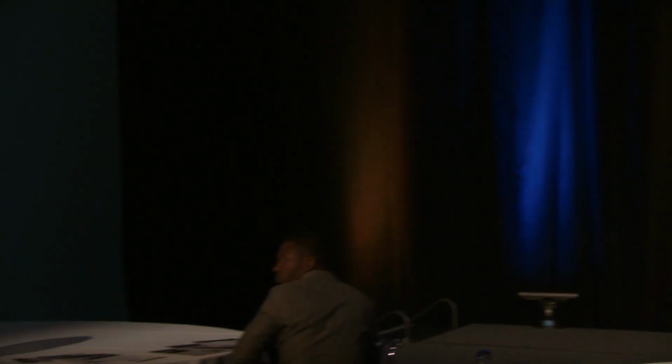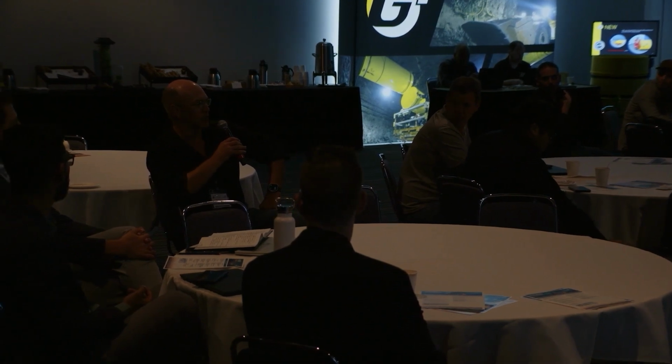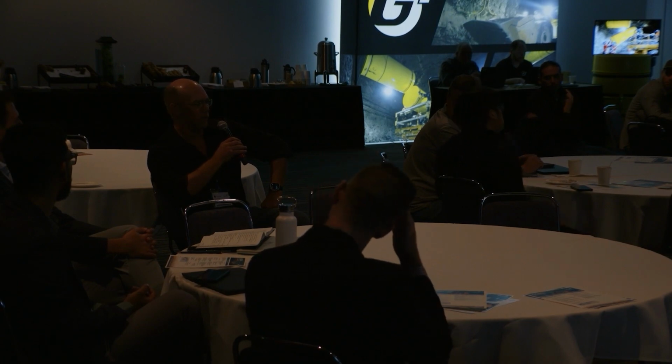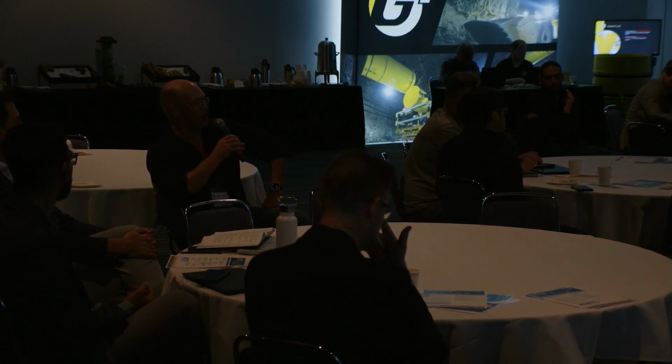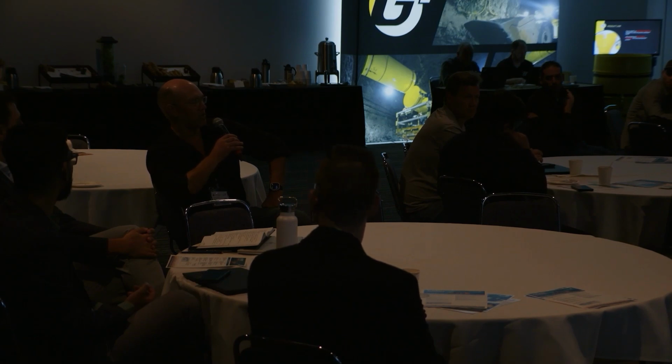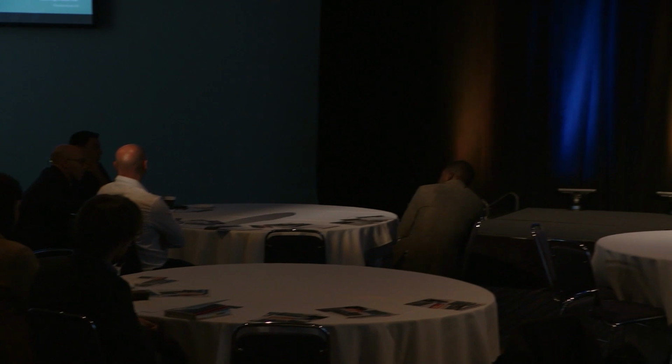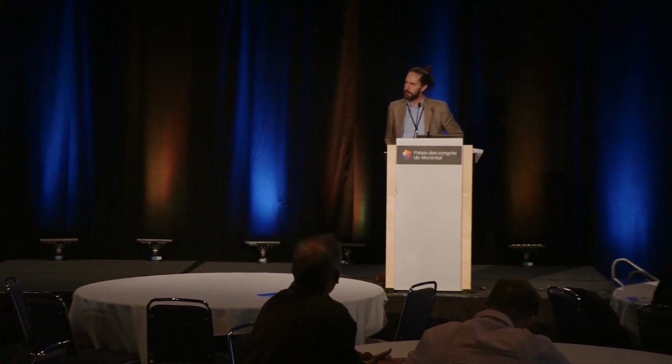Yeah, just to comment on that last question, the estimation of output of any engine has always been a bit of a point of contention, and there's lots of studies to suggest what that may or may not be. But with diesel equipment, we've found by far the best way is to measure the fuel usage. With electric machines, I don't see any reason we can't do the same thing. For example, if we've got an electric machine with a 300 kilowatt hour battery, and the battery is depleted in 3 hours, the average output of that machine is 100 kilowatts. And that can be used to help validate any sort of utilisation figure you might come up with. So ignoring any potential energy changes with hauling rocks up heights, that really is a pretty good value to start with.